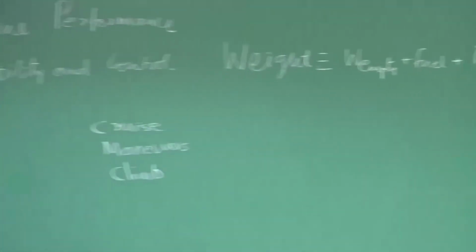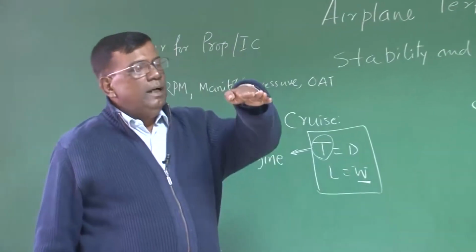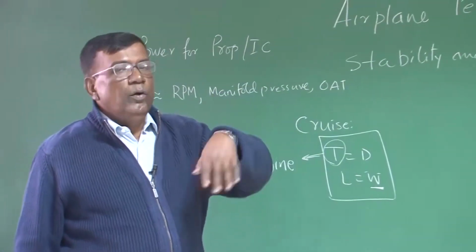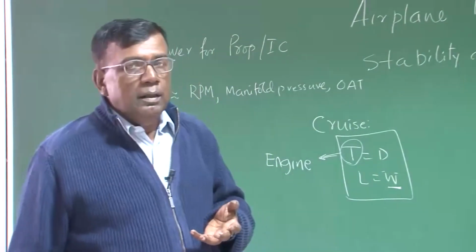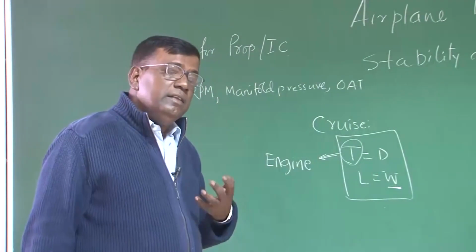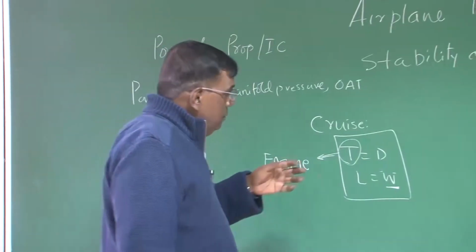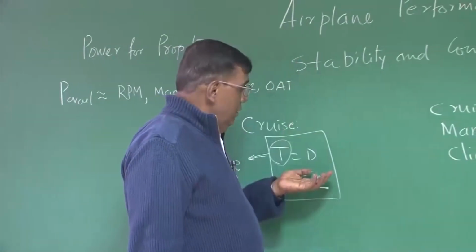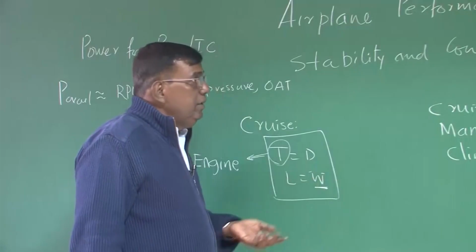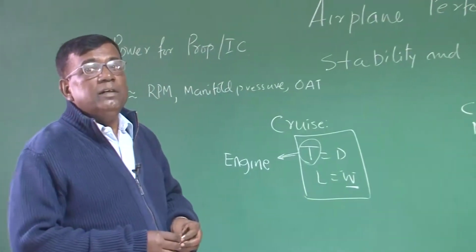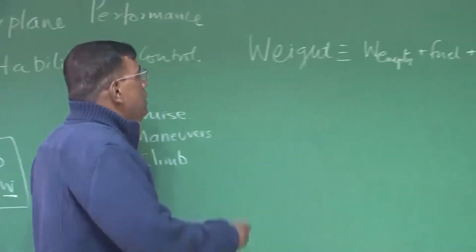Why weight is important, you could see here. After all, when I am cruising at an altitude, if the weight is more, I need more lift, right? More lift means I achieve that lift either by speed or angle of attack. So the performance will be largely governed by the weight of the airplane. If your weight measurement is not correct, then your performance estimation will not be correct. So we need to know how to measure the weight. This is one.